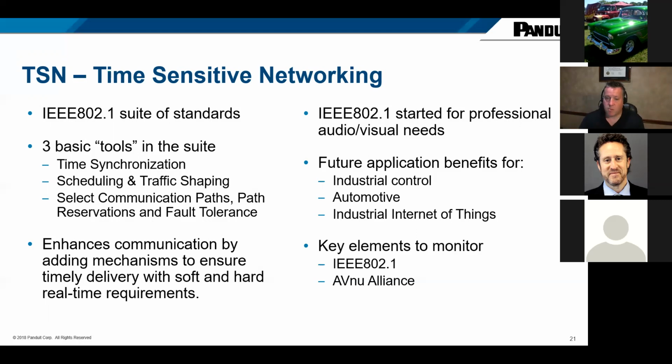However, until TSN came around, all these protocols, including CIP Sync and other technologies out there for time synchronization, were best effort. Okay, they were pretty reliable. You know, obviously, we're doing some pretty cool things on plant floors with it, but they still are best effort protocols. TSN actually guarantees determinism and can be applied to standard Ethernet as well. So that's the big thing.